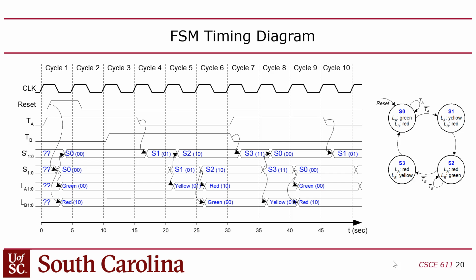And this is the part that I find to be a little confusing. Because what's happening here is that you're always going to see this one cycle delay between your input and your state change, right? Generally, assuming, of course, that your inputs are changing on the same clock edge as your state changes. Now, let's see, is this rising? Yeah, this is rising active. I can tell because you see S changes just after the rising clock edge, right? So this is a rising clock edge system.